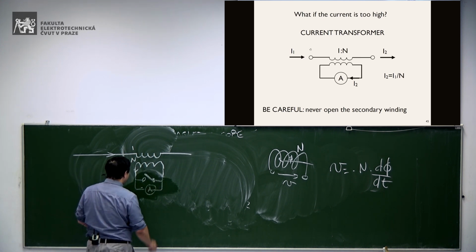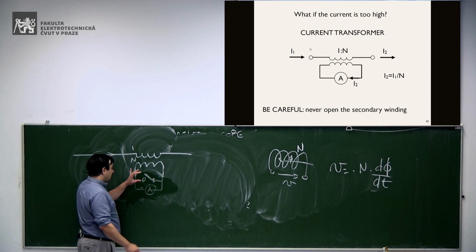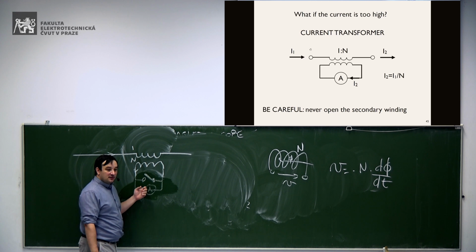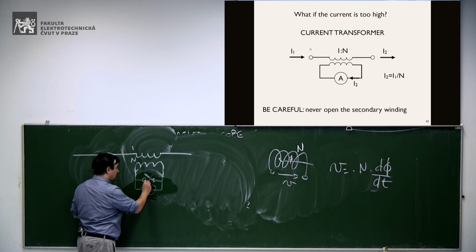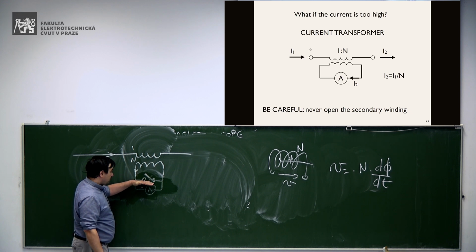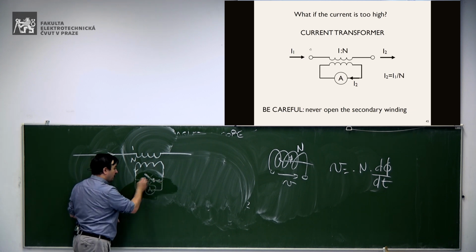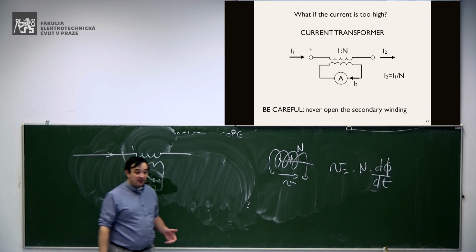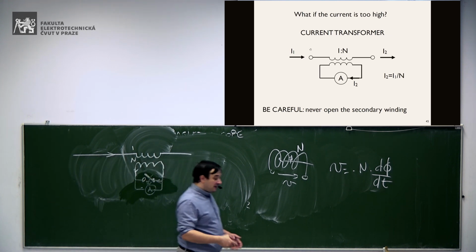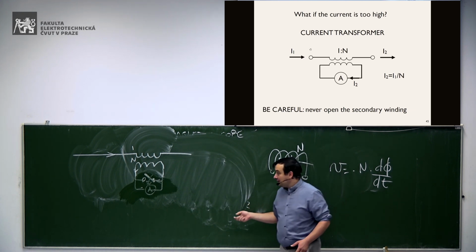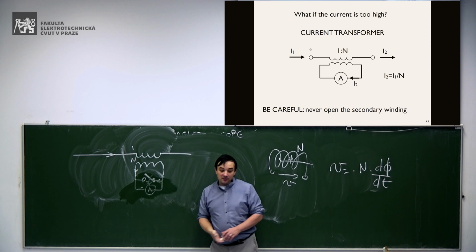Because they tell you, sometimes they even write it, like before removing the ammeter, always close the switch. Because in this way, you can close the switch, have a current flowing here, and always keep the short circuit running. Always have the current running in the short circuit, and then you can remove the ammeter, okay?